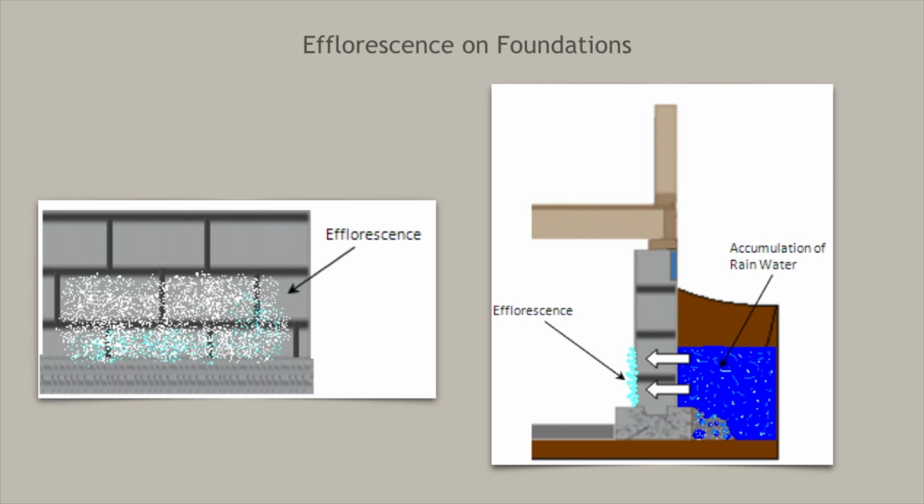As a home inspector, if you notice efflorescence the day of the inspection, this is or was a sign of water accumulation along the foundation wall. This is the first sign of water infiltration.